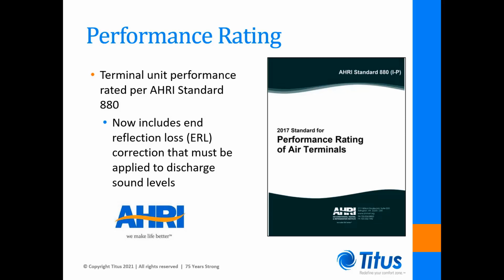As far as changes to industry standards, there were no real changes for many years until AHRI Standard 880 was revised in 2012. This is the rating standard that tells manufacturers how they should present performance data gathered from tests run in accordance with AHRI Standard 130. Manufacturers were now required to add end reflection losses, or ERL, to the discharge sound power levels of all terminal units. So what exactly is ERL?